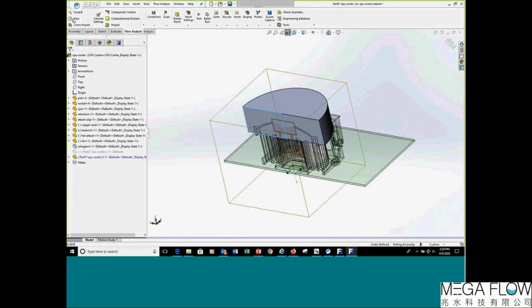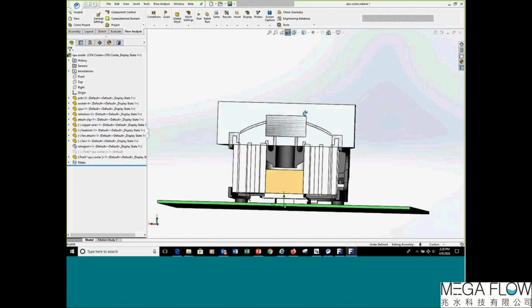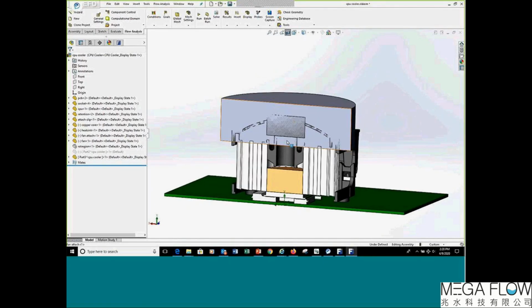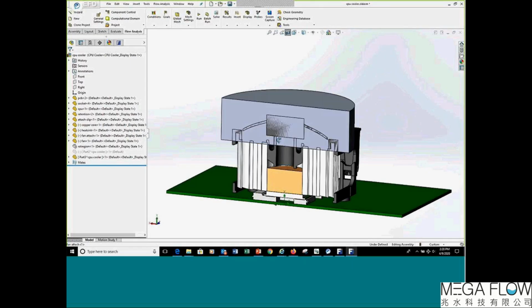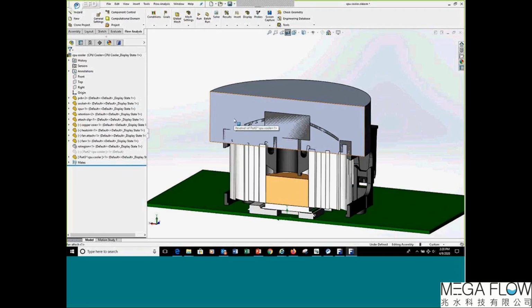Okay, and I've just built my rotating region part. Simply said, it's a 2D sketch revolved into 360. It's a hockey puck, basically, with no real shape to it. It encompasses the entire fan and a little bit more. But again, very simple. I did it really quick just to show you that, as far as making the steps in there, I could be more precise, and I'm going to do that. I'll show that anyway. But this is a simple rotating region part, okay?